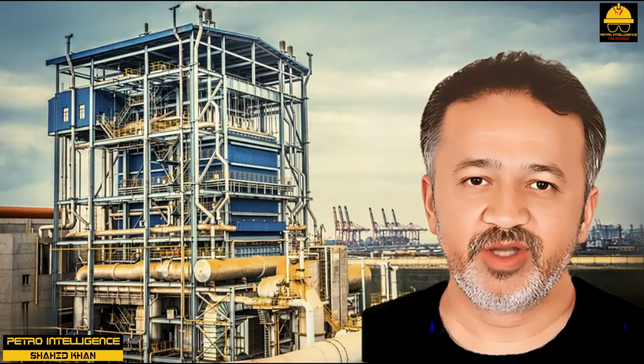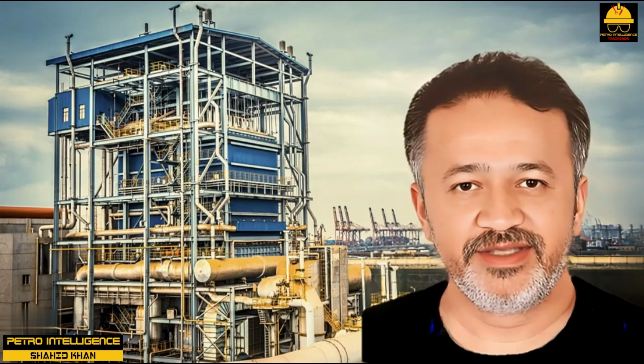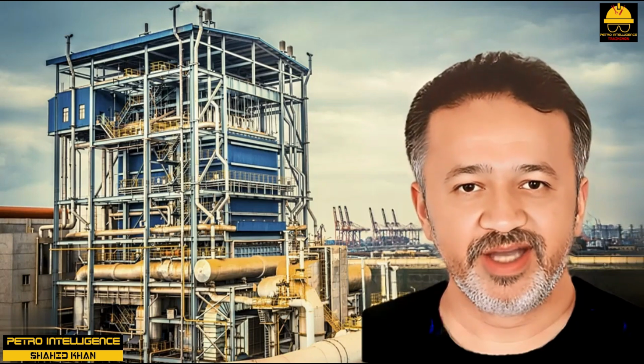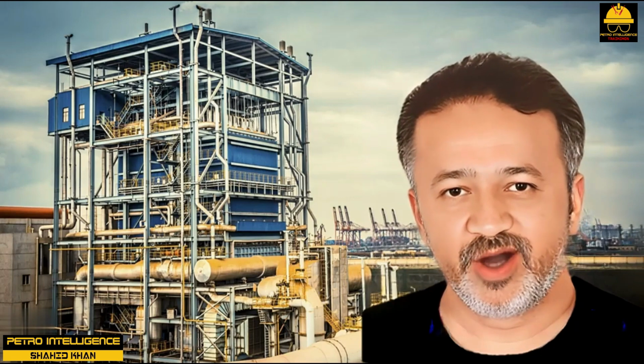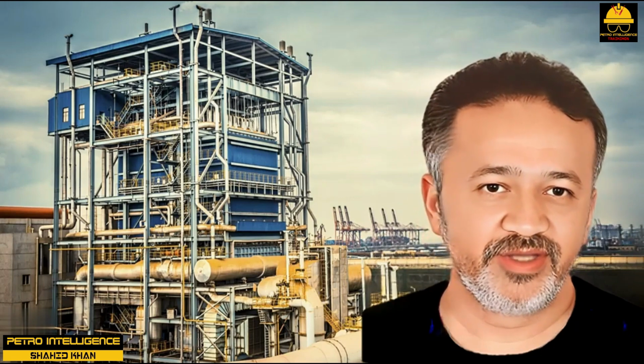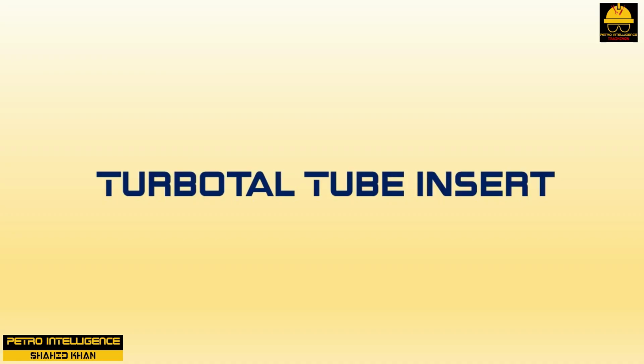However, there is also an associated increase in tube side pressure drop of about 3 psi per pass at tube side velocities of 3 feet per second. The main applications for spiral so far have been oil refinery preheat trains for CDU, VDU, FCC, water treatment feed exchanger HTS units, and high tube velocity applications as found in reboilers.